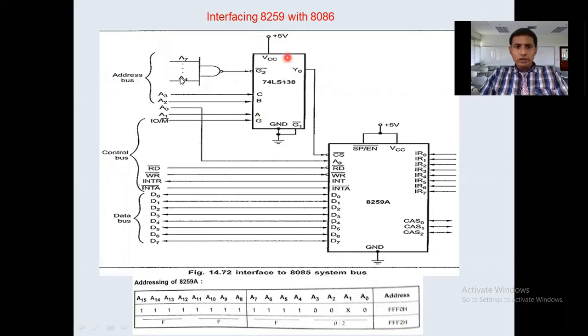The address decoder will take the set of address lines from the processor and it will generate outputs, and those outputs are used to activate the peripheral devices. Generally, the address decoder not only activates the peripherals, it also provides addresses to the peripherals. Let us see how they are connected first, then later see what the operation is.